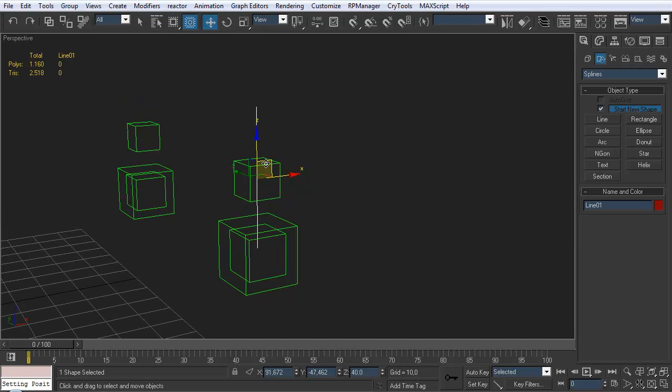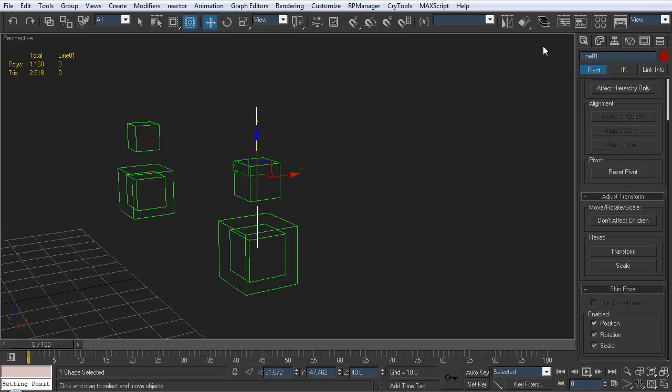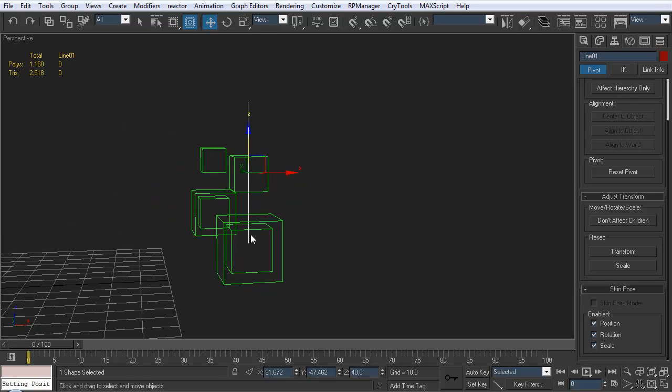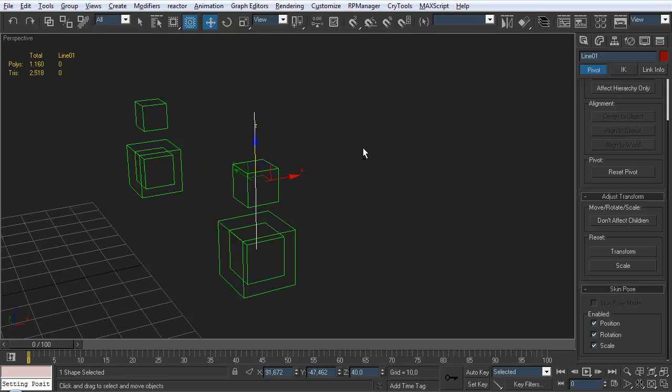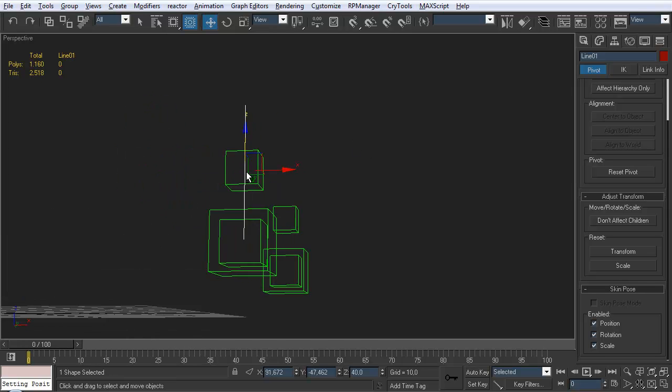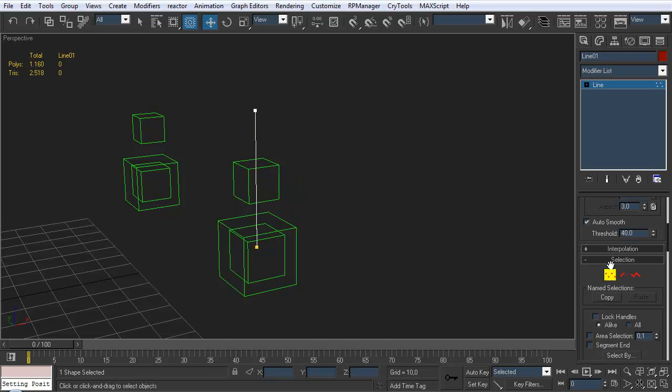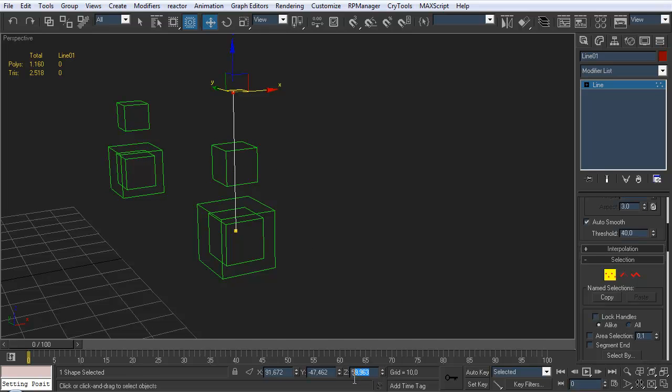This line is the line along which the suspension anchor will be moving. Note that this line is the actual travel our body will be allowed to do. We might want to make this a little shorter since we're working with a sports car here that has little suspension travel. The way we do this is just go into the spline's vertex mode, select a vertex, and let's say we only want to give it a travel of 20 in every direction, so we need to type in 60 and 20 at the bottom. There we go.